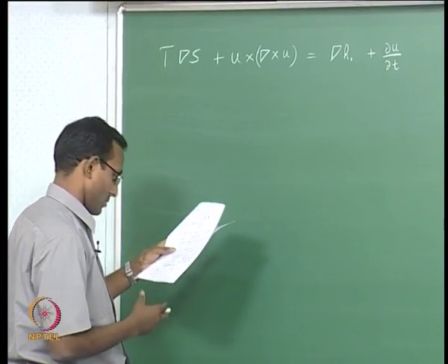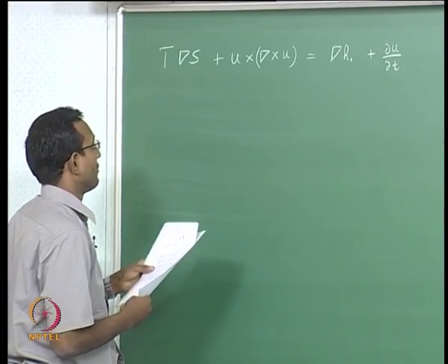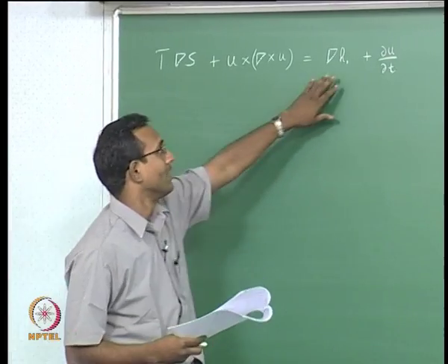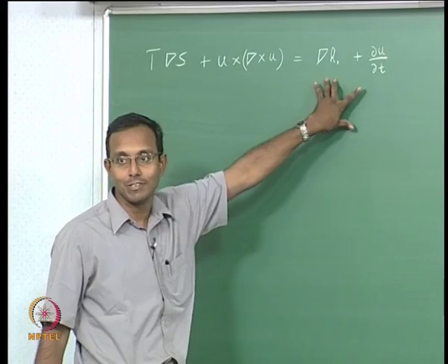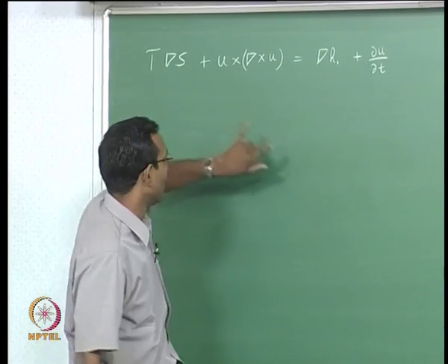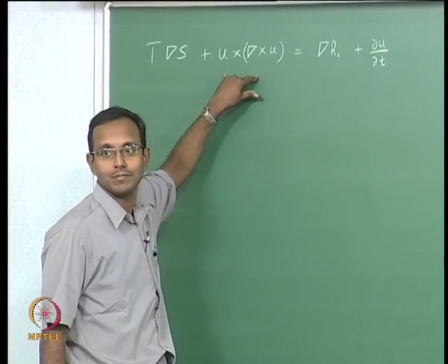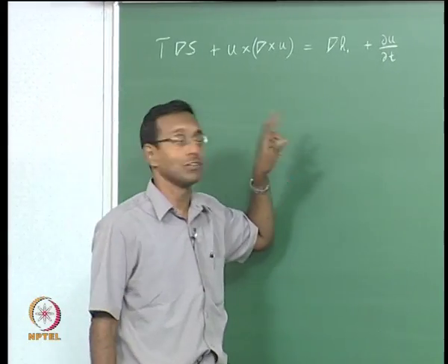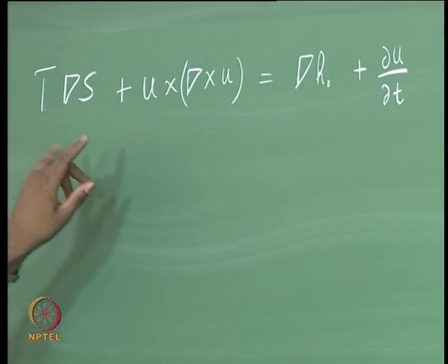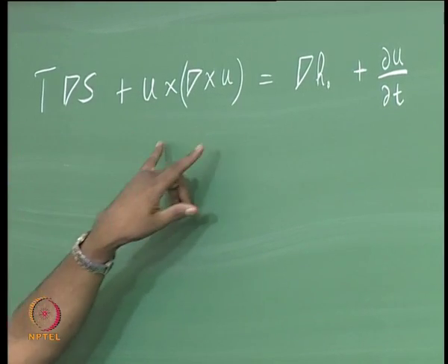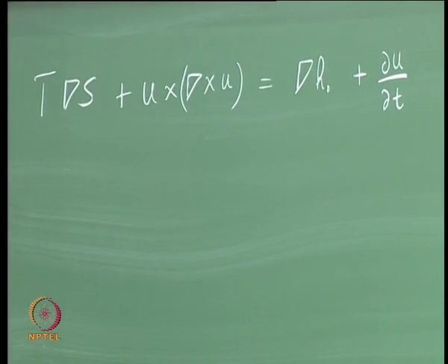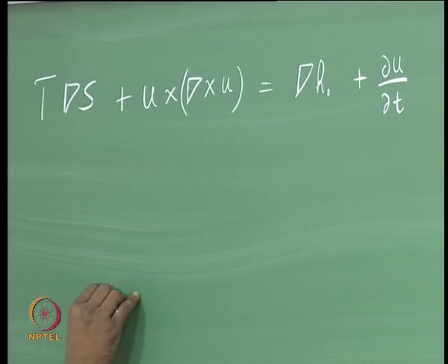Now, if I look at different things, even if I have isentropic flow and isenthalpic flow, if my velocity is changing in time, I may produce vorticity due to that. That is one more thing I can see from here. Even if I increase velocity even isentropically, I am going to have a case where I will have vorticity produced. That is one more statement from Crocco's theorem. Now, we will see some examples.